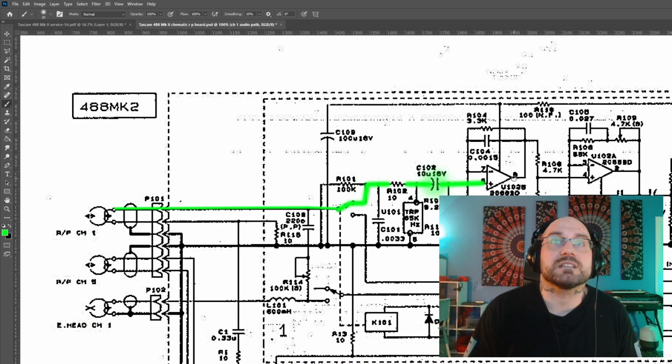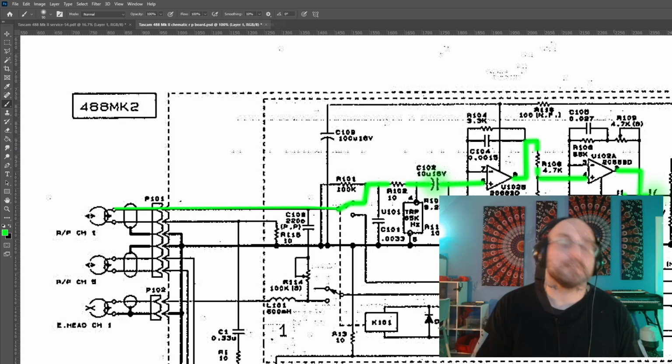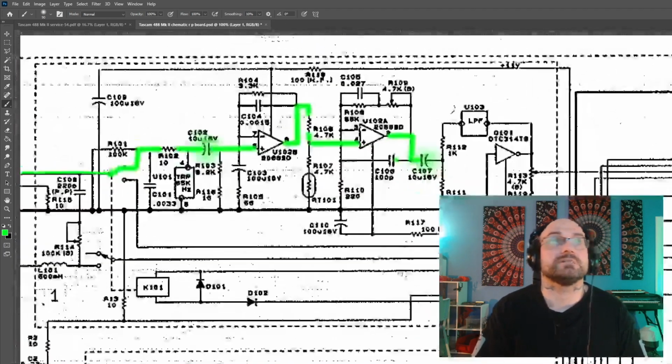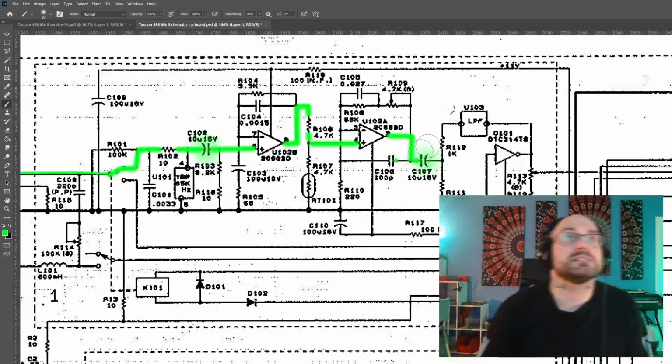The audio path is coming out of the tip of the triangle and it's going to this junction here. Now this junction is all feeding back into the feedback loop and everything, so I think it's going through here, past this resistor. There's a little voltage divider here into the input of this operational amplifier, and it's coming out the tip there. Now obviously that signal is going to a variable resistor here. This will be one of your trim pots. In fact, this is going to be all off to the part of the screen that you can't see because of my face, isn't it?